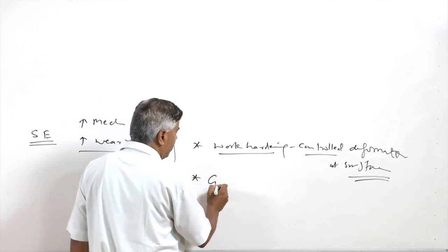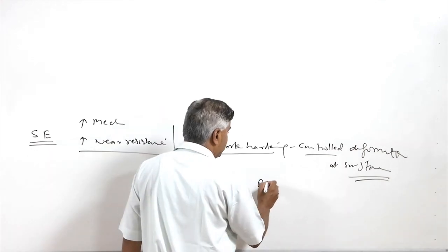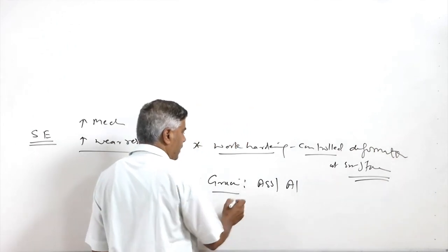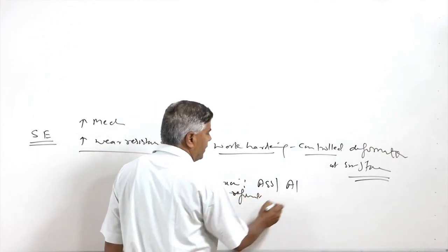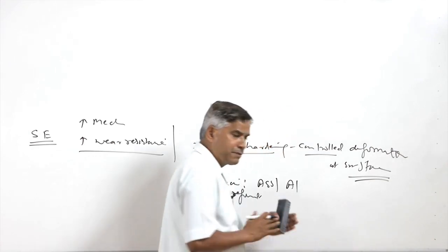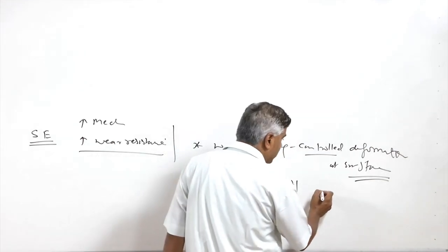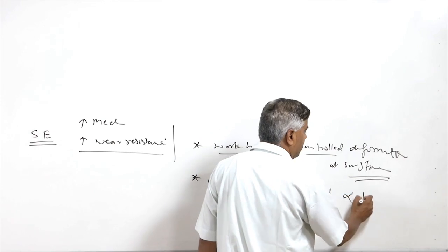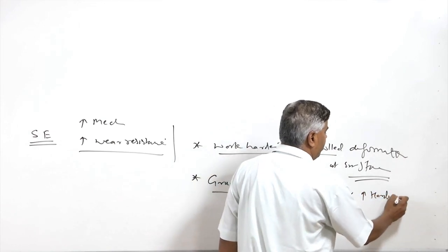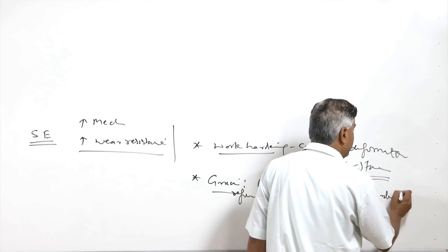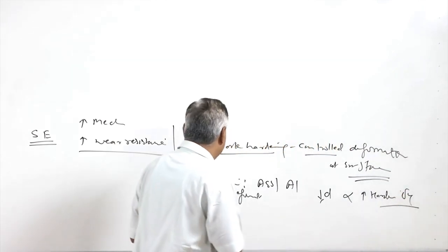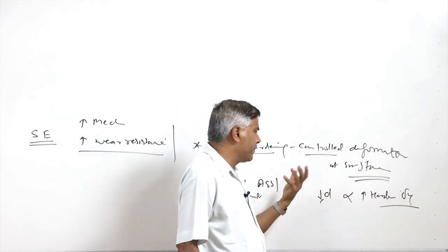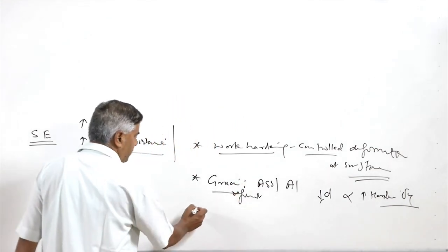Another one is the grain refinement in some of the systems like austenitic stainless steel and the aluminum alloys which are non-heat treatable. The grain structure is refined. For this refinement, thermal as well as mechanical methods can be used. We know that as soon as the average grain diameter is reduced, there is an improvement in the hardness and an increase in the yield strength of the material. So the near surface layers grain structure is more refined in this approach, so that improvement in yield strength and hardness can be realized.